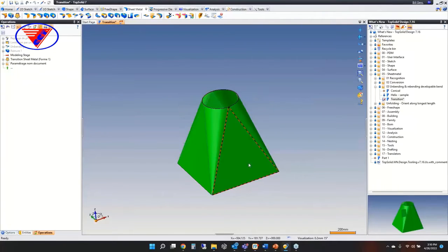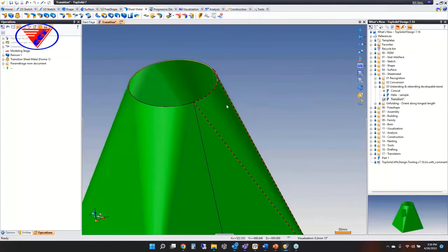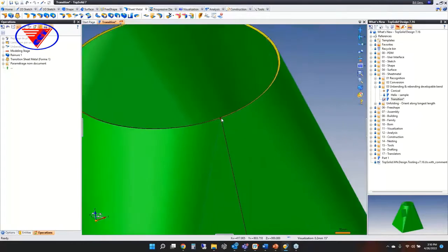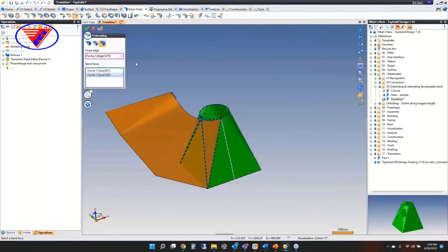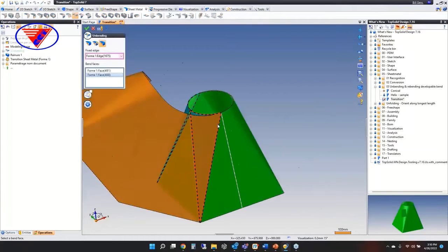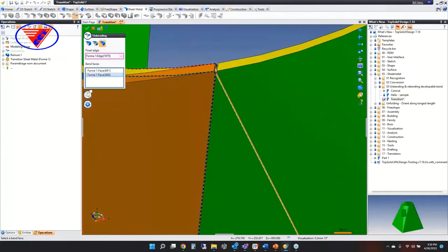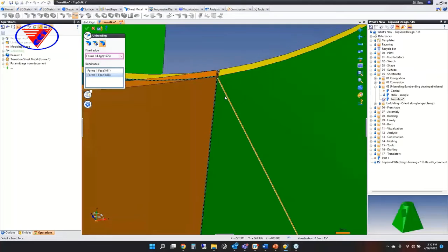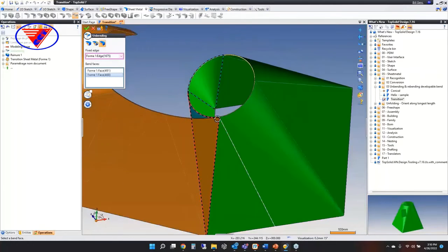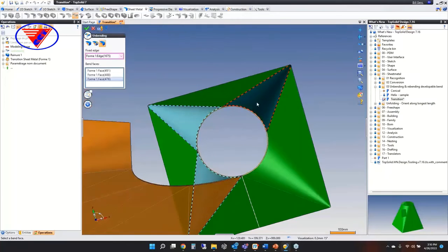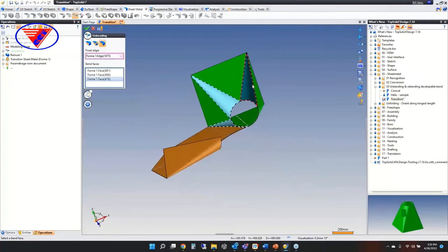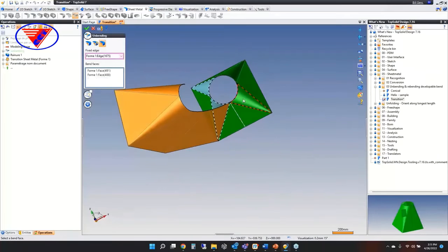So we have our transition part from round to square in this case. All right, again, I had to split it so that we could create a flat pattern for it. Then we go to unbend it, and I'll go edit the unbend so you can see. So choosing my fixed edge, right? In this case, I chose the outside edge in this front face, and I chose other bend faces to unflatten. I could add this one to it if I wanted to, and unroll that. Doesn't really matter. Okay, we could add that one. Just unfold and unfold.